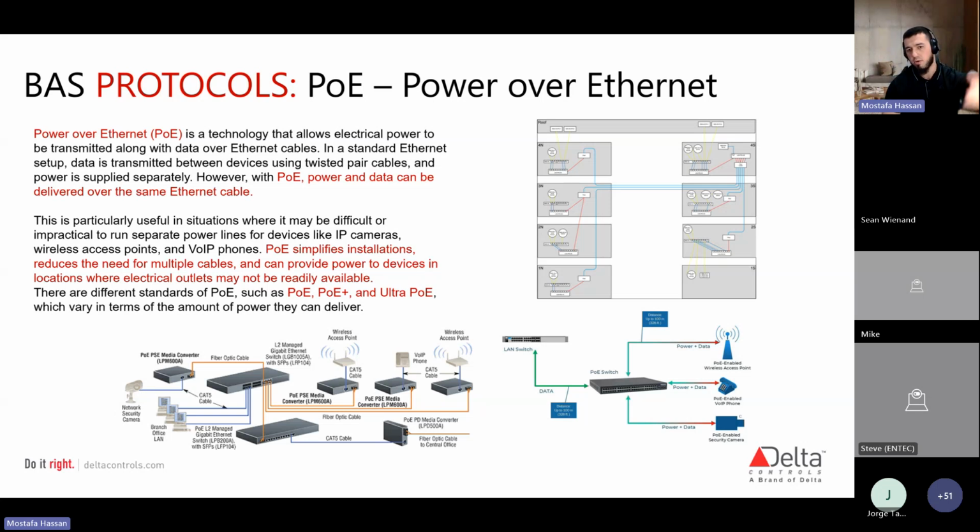If an electrician's creating your conduit or riser for you throughout the building, you just have to run two separate conduits, two separate risers. It's also flexible, especially for remote applications, since you don't require a nearby electrical outlet. These and other benefits have led to a sharp increase in PoE's popularity. Now, obviously the limiting factor has been power, right? Can the grid handle all these buildings turning to PoE? That's really the question for the future, especially with Local Law 97 and things like that.